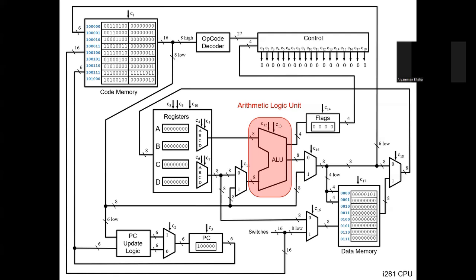The two lines mean that you can choose between a set of basically four circuits which do different operations, and those circuits can actually be abstractions of multiple instructions that can be implemented. So you can have an adder-subtractor in one circuit and you just need one bit to switch between those operations. That's basically how the arithmetic logic unit works. It does the computation in the CPU, the actual computation, and it contains the circuits to do that computation, right?